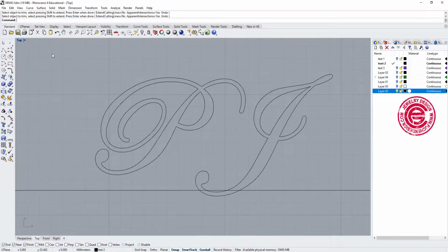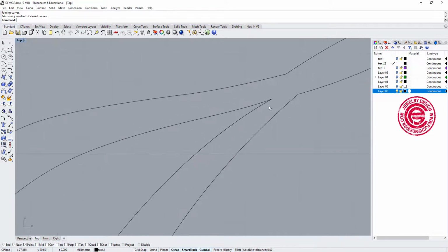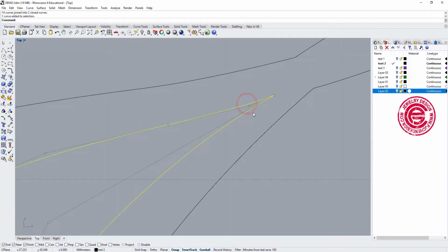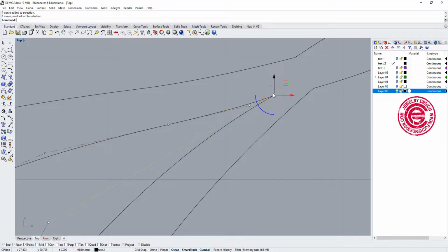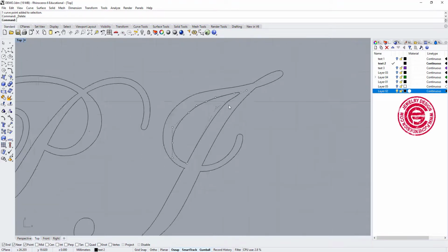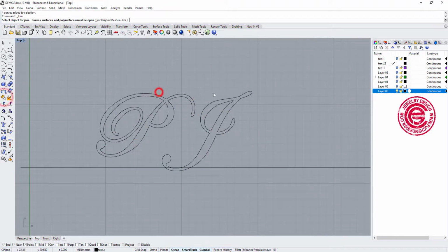Let's go ahead and join this one here. We also need to enlarge and look specifically at those points. Sometimes those points will cause problems. Usually what I like to do is make them a little bit rounder. That's one way to delete the control point, or you can give it a fillet there. All right, so we want to join the other one there.